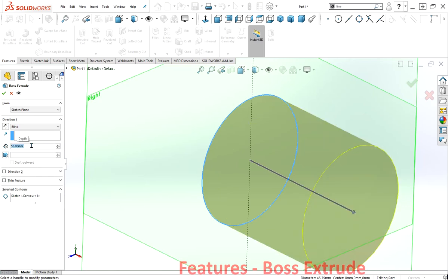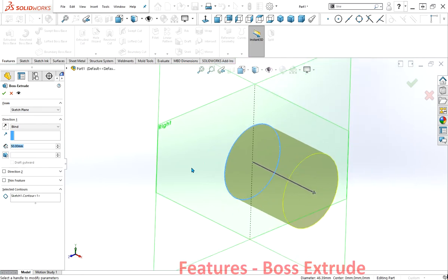50 units. Whilst I'm talking about units, it should default to MMGS down here, okay, but you can change that, but not in the middle of a command. I'll show you that a bit later. Just worth checking. If you don't get millimeters shown up here, it might say inches, etc. Stop what you're doing and just quickly change it down here. So here we can set this exactly.